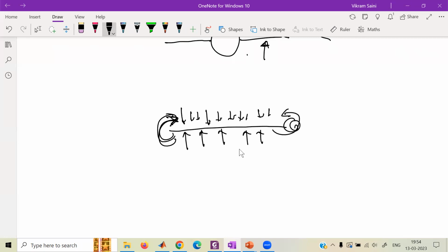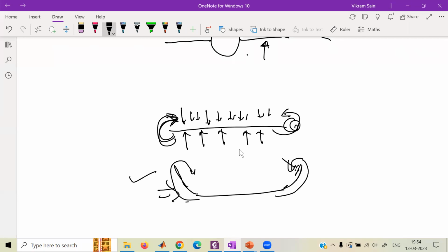Now what you do is you put obstacles into the flow, something like this, right? Now there will be some increase of pressure on these parts and you don't have an easy path to go like this. So it eliminates the vortices, not completely, but to some extent. That's the mechanism. Okay. Actually, it's preventing the lower air from coming up. Yeah, that is the idea.